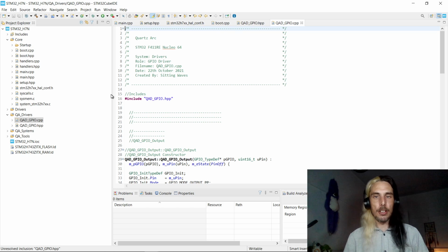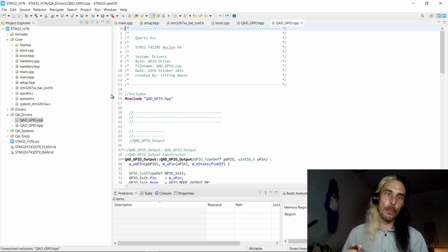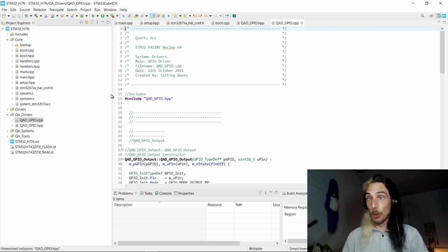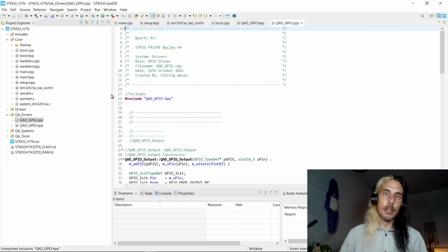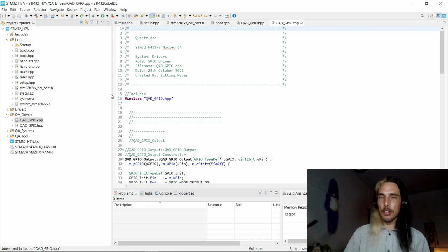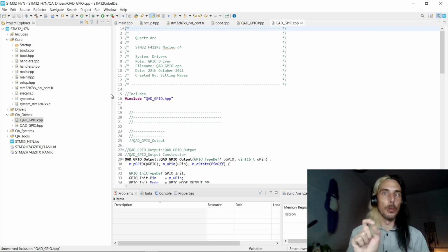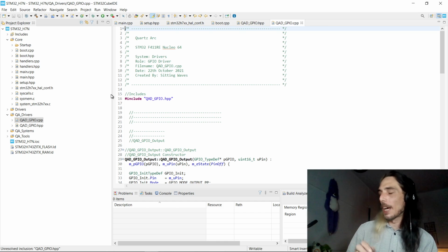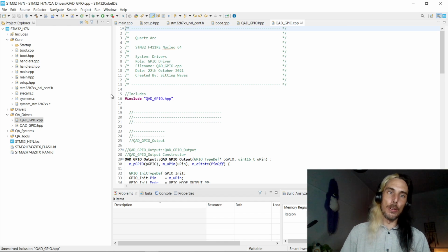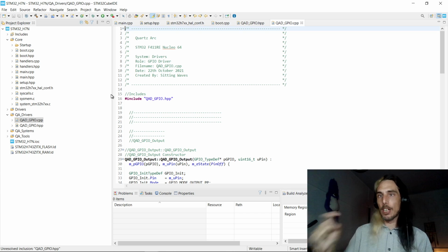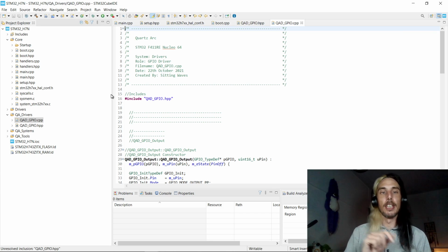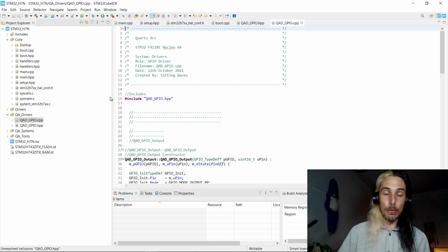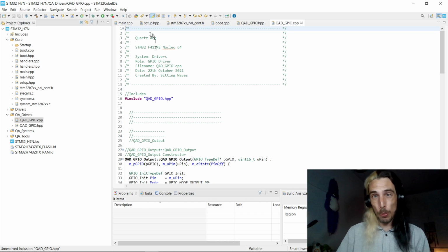There will be certain things that will change. So for example, the particular registers that we access for TX and RX for the UARTs will be different. The F4 device has just a single register called DR, or the data register, that it uses for both TX and RX, whereas if you're dealing with an F7 or H7 device, it uses a TDR, or transmit data register, for transmit, and a separate RDR, or receive data register, for receiving. But we'll see how we modify that during the next stream for this series as well.